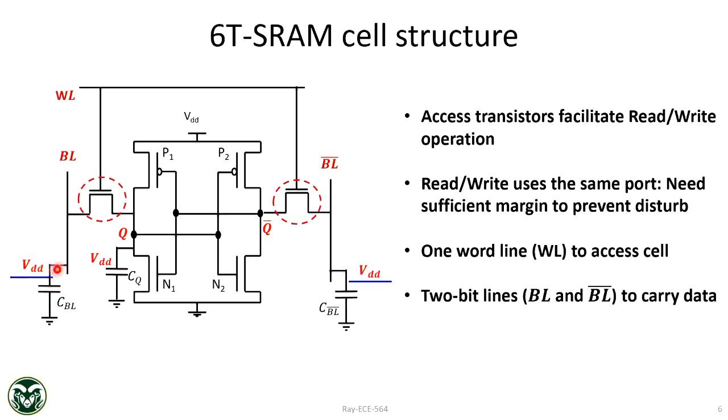That means a little bit of change from the bit line will completely charge this capacitor. Charge here means with respect to VDD. VDD is the maximum voltage in this cell. Whenever you charge a capacitor to VDD, that means it's fully charged. We'll talk about some of those charge sharing calculations: when this capacitor becomes fully charged, how much charge is lost from the bit line. We can easily calculate that based on the capacitance values, and in your homework you'll do that.